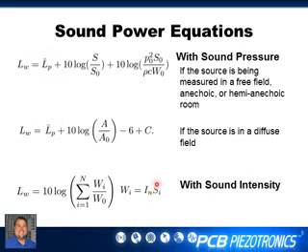And in the last equation, you see sound intensity, which is directly derived from sound pressure, both from the sound pressure and the particle velocity, which is derived from sound pressure. So no matter what you're doing, whichever one of these equations you're looking at, it starts with a sound pressure measurement with a microphone.